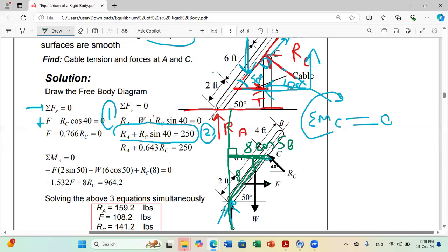While we calculate the moment, we don't consider the weight? Of course we do. So now we will consider the moment of the weight about C. Can you have 3 unknowns or 2? No, the weight is known. You know the weight, it is 250. You know the value, but you find its moment. It will not add an unknown, but it will add a term to your equation.